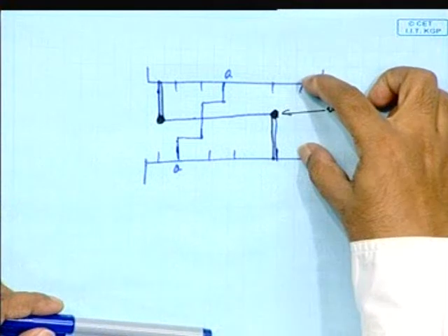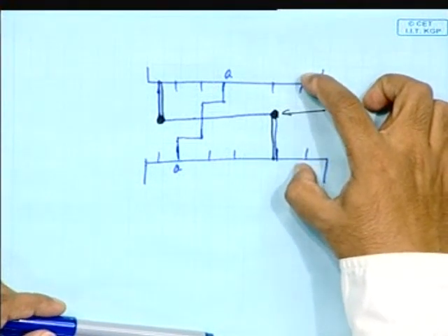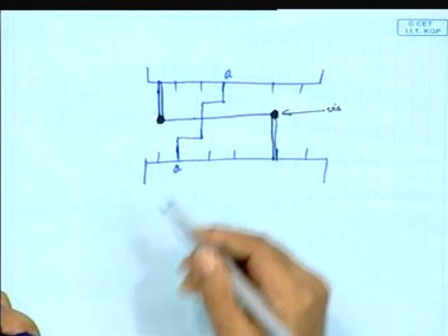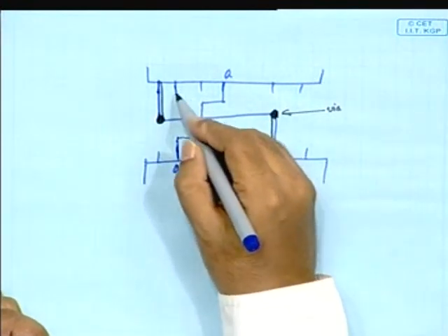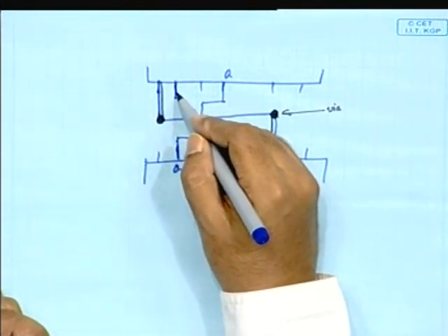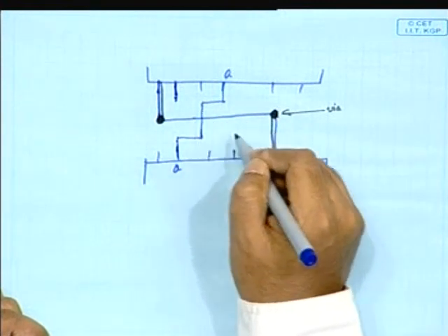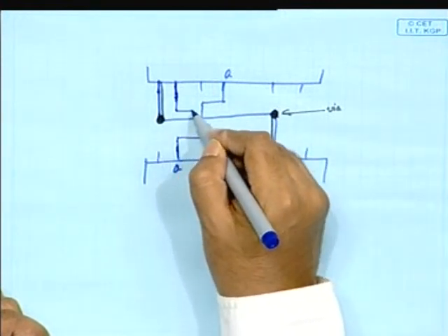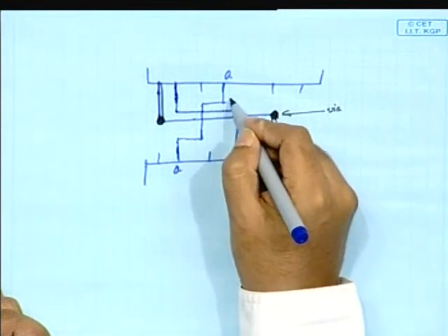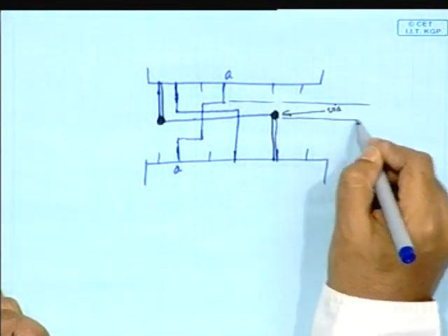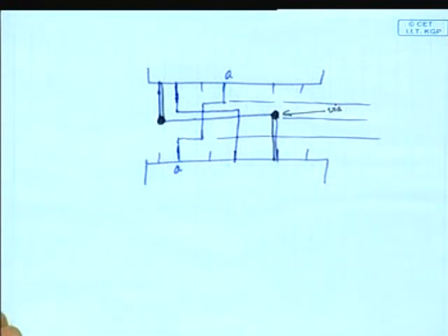Now that's kind of nice, right? So we say that only with 2 layers. But what is the trade-off with just 2 layers? The space that you require for the routing will grow, right? Because the next time when you want to connect this with this, okay, how are we going to connect it? Can we just reuse some of these? No. So we will have to again go something like this. So that's bad. Now we have 3 channels. This is one channel, this is one channel, this is one channel, right? So it's going to grow as the net interconnection becomes more complex.